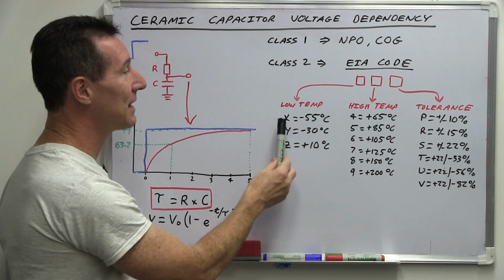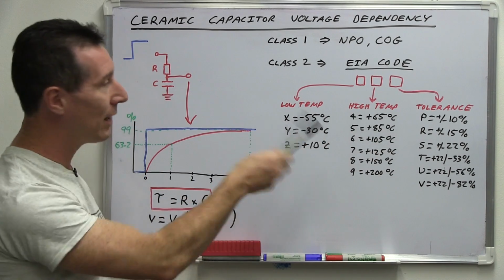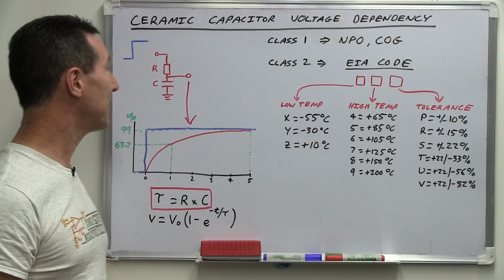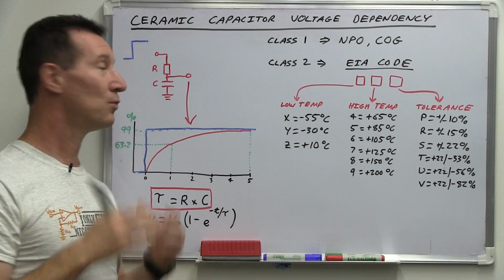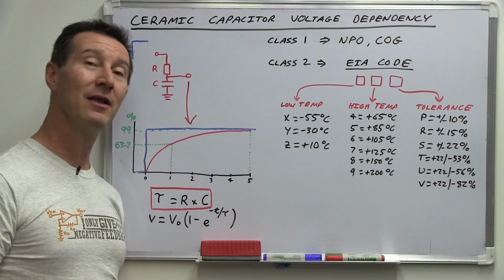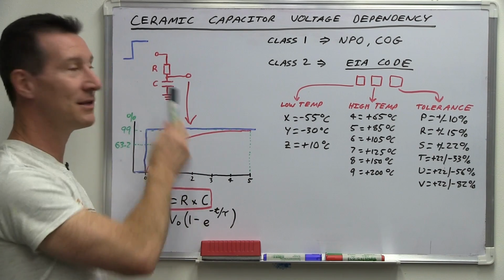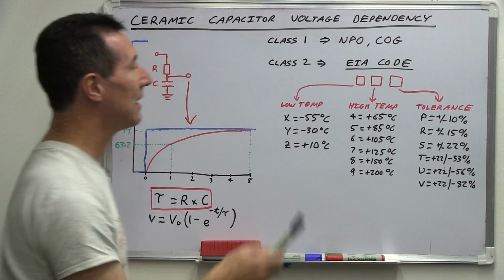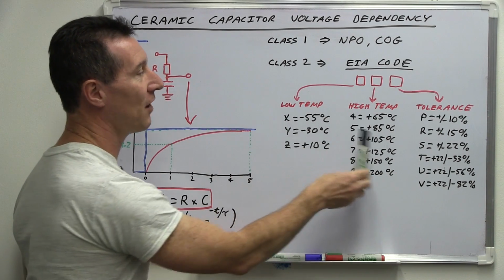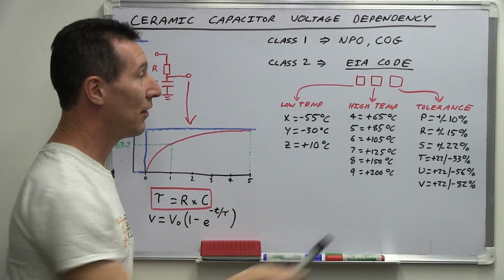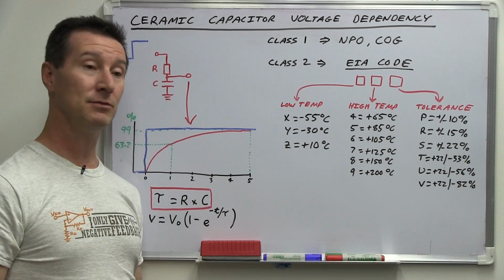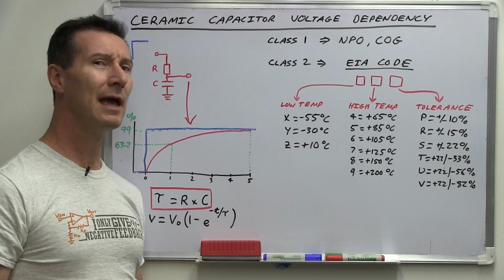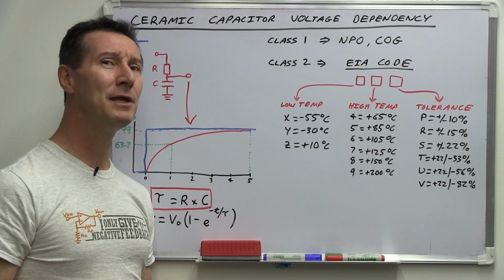What we'll take a look at today is an X5R or X7R capacitor on the bench, and we won't be taking frequency into account as well. It'll be nothing to do with that. It'll just be the capacitance, this tolerance figure here. So if we have a look at, say, the X5R capacitor we're going to look at on the bench now, it should measure plus or minus 15%. Does it? Well, yes, and maybe no.